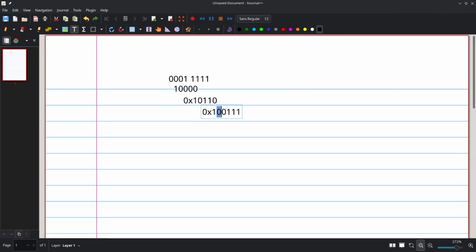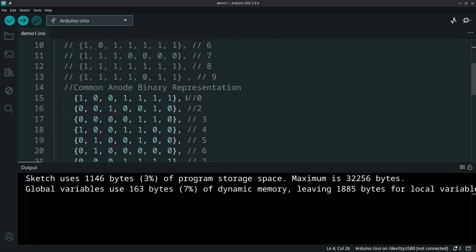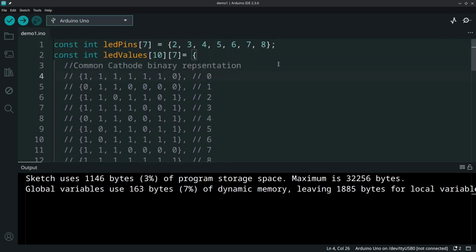Coming to our normal code here, we also have A, B, C, D, E, F, G, right? This is A. This is 7 bits. To make it 8 bits, we add another 0 to it. Then we have the first 4, which is F, and 3 represents the other, though of course you can alternate them. That will be 3F. This is F, this is 3. So it depends on the pin arrangement. So that we have 3F. That is for common cathode.